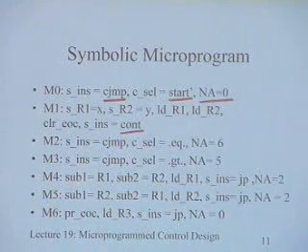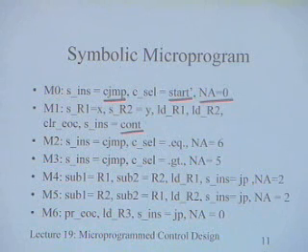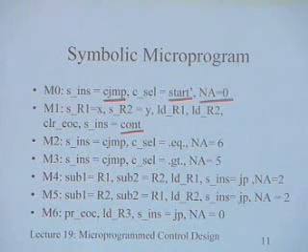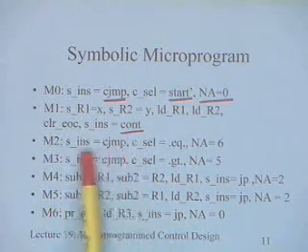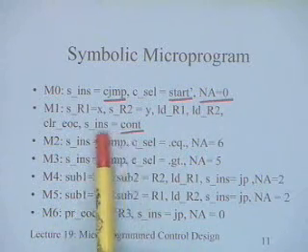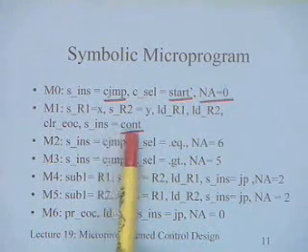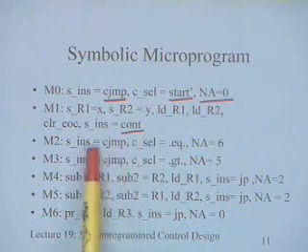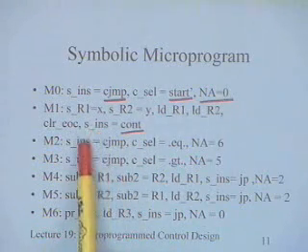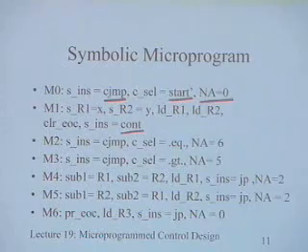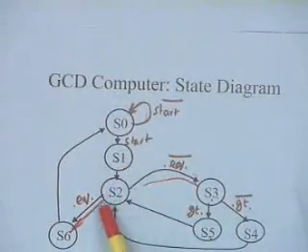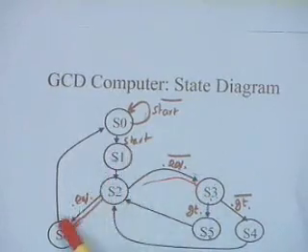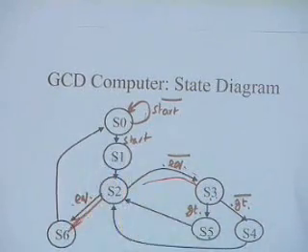Okay, now there are certain issues related to the timing and the way the circuit operates, and these are extremely important in the design. Why can't I do this operation sequence? After all, here I was not doing anything as far as the sequencing is concerned. I just had continue over here. Why can't I push this over here? That means, in terms of timing, in terms of the state diagram, I can perform the branching right over here. Instead of performing the branching here, I can perform the branching right at S1.